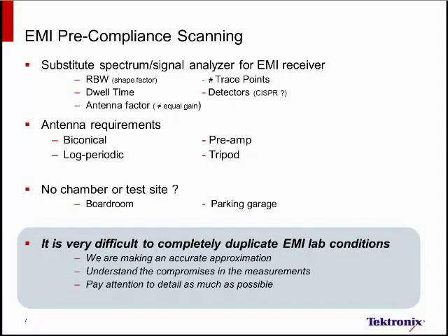People are often a little bit confused about this particular situation because if you didn't have an anechoic chamber, are the measurements valid? And the short answer is yes. We may have to use a boardroom. We may be able to do it in our lab if the lab is RF quiet enough. Or I've even seen people make measurements in a parking garage.